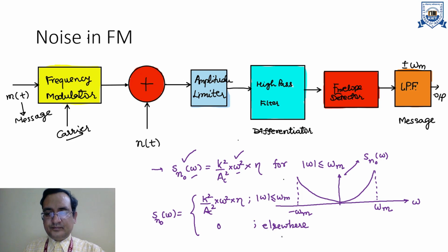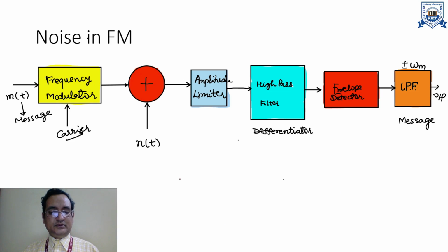As the power spectral density at the output of the filter has a parabolic relation between the frequency and PSD, there is another conditional effect generated in the frequency modulated system, which is known as the noise quieting effect.